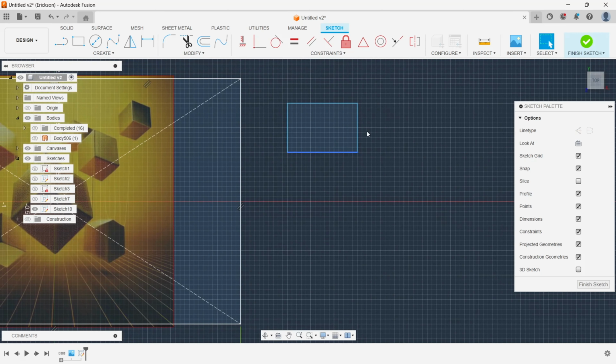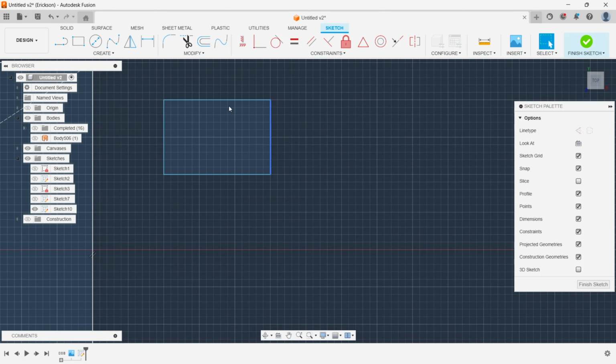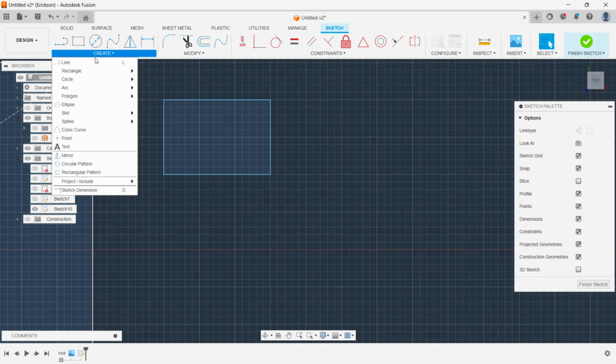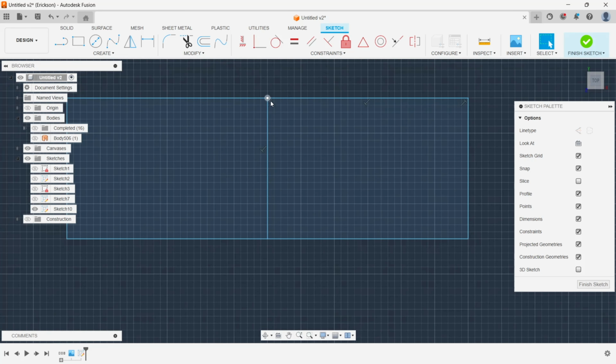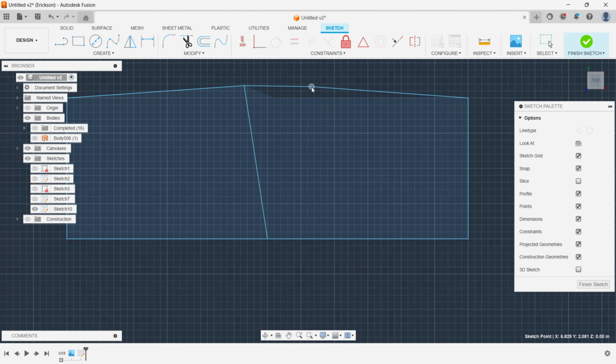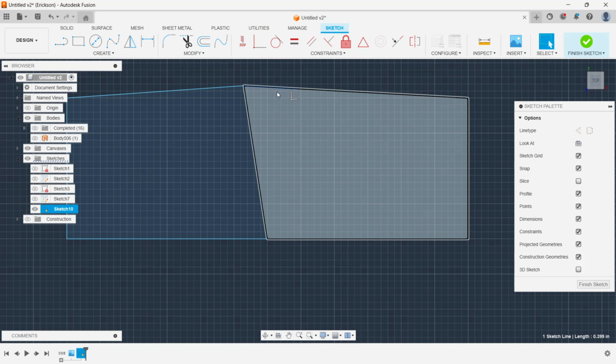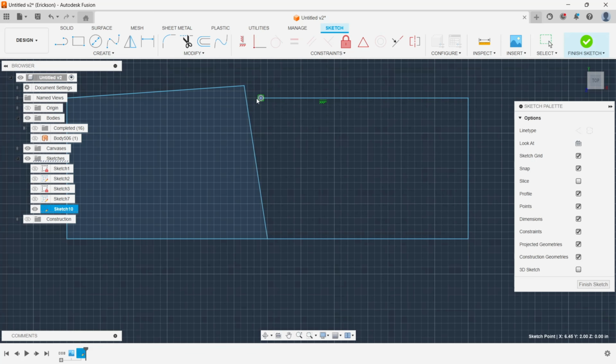So let's do the same thing. Let's do a line. I'll show you a different way of doing this. If I do another box with a line, you'll notice that these perpendicular constraints are in here too. So I'm going to delete those. And now if I move this, everything is still connected. Actually, let's delete that and we can move this to here.